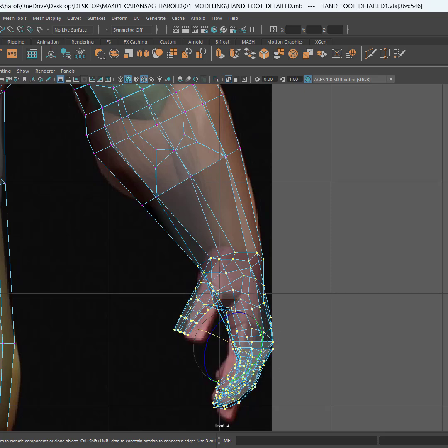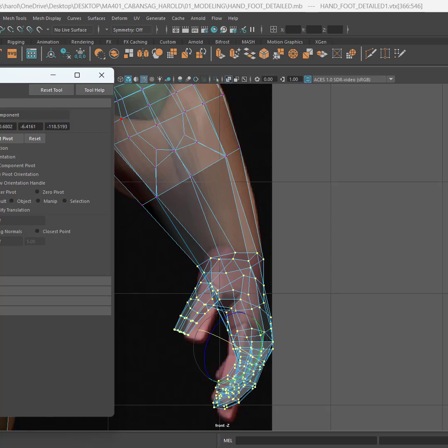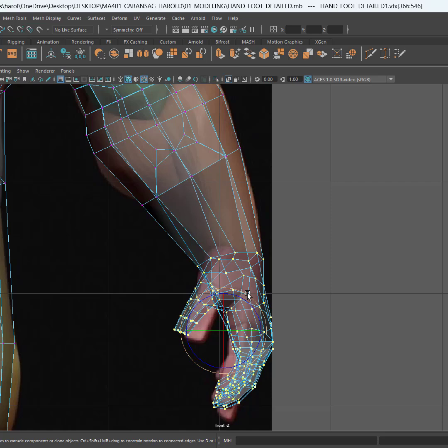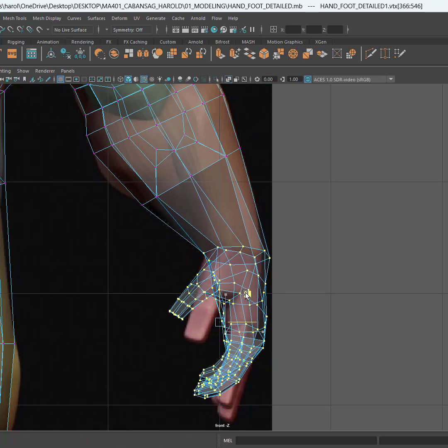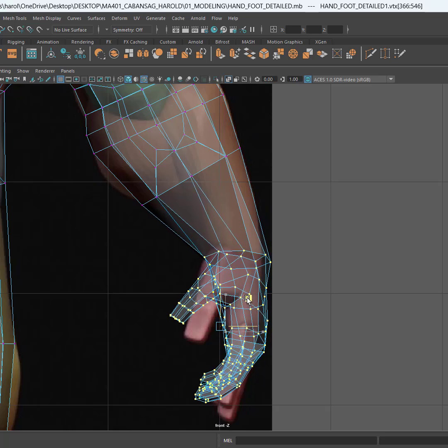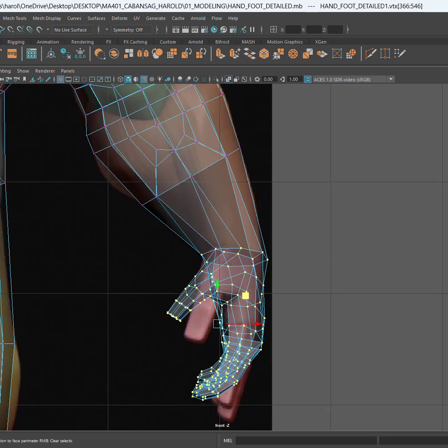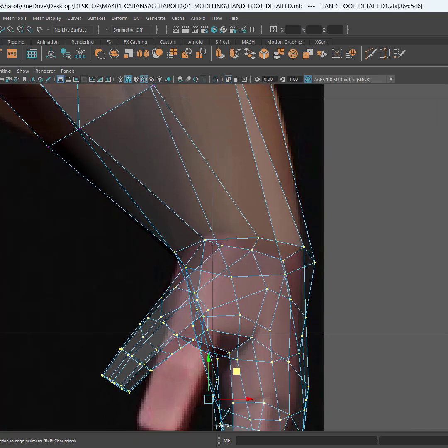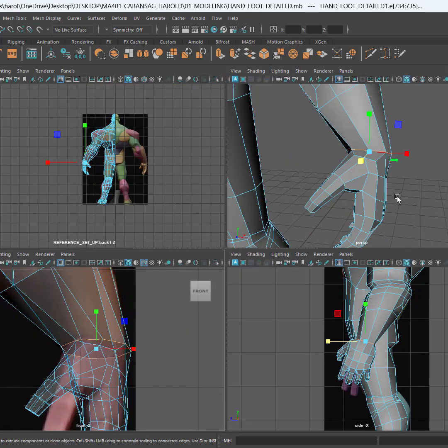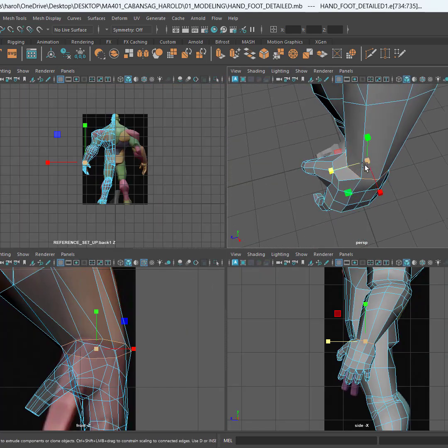As you can see, my rotate tool is component oriented. Let's go object oriented. Close that, and then W there. So let's say we're okay with that, and then I'll just, having those edges selected, I'll go for the scale tool here.